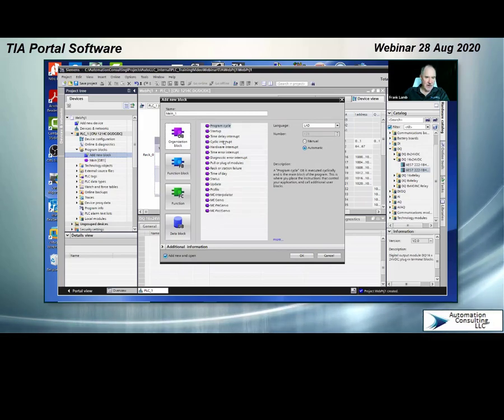They do have numbers behind them, but you can pick your hardware interrupt and it'll just pick it by type. You don't want to rename this. You can select a cyclic interrupt, which is typically, again, here in the 30 range, right? I can pick 35 sometimes is all you get in Step 7. I can pick one of those.